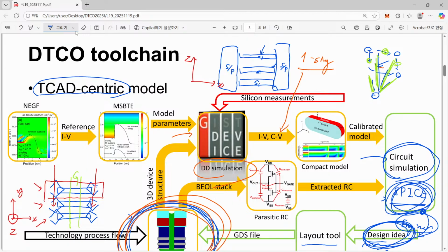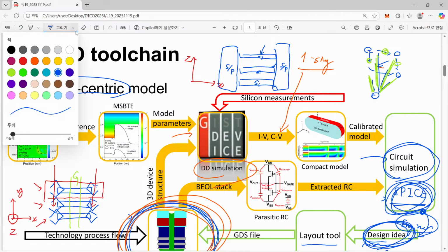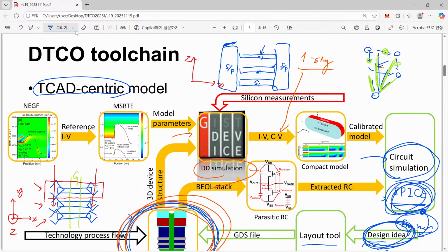My question is, previously when we had FinFET, even in that case, we were worried that maybe they can interact with each other, especially in terms of their contact resistance. However, now when we have a nanosheet MOSFET, it is really clear that they are interacting. Where can you find the source and drain contact? Here we have a source and drain contact, and here we have a source and drain contact.